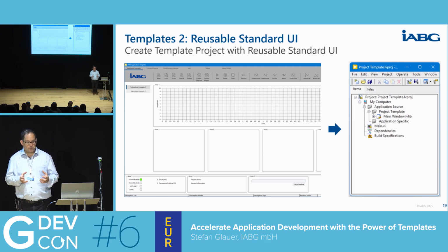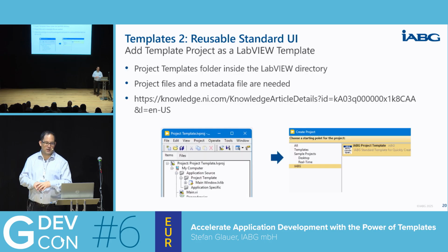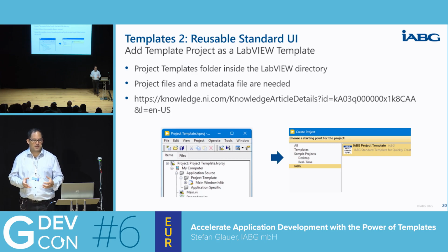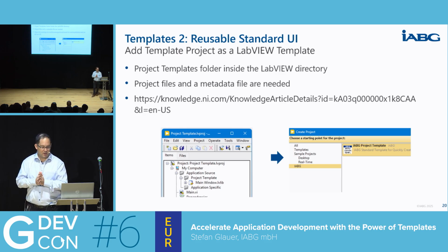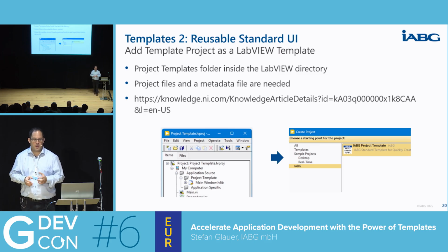And what we did then, we added this to the LabVIEW project templates so that we can start it with one click. To do this, you need to copy the source code and create a metadata file and put it in the LabVIEW project templates directory. And there's a great NI knowledge article about how to do this. And now we can create a new project and have everything set up for us just with one click.